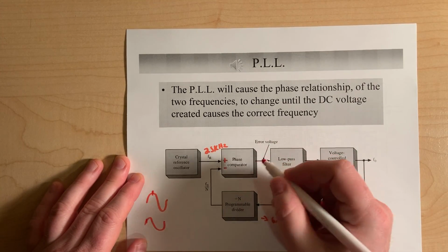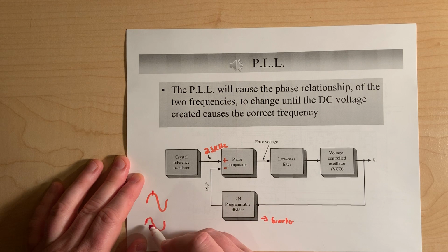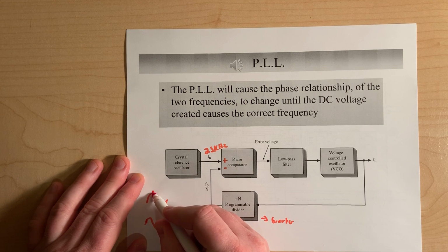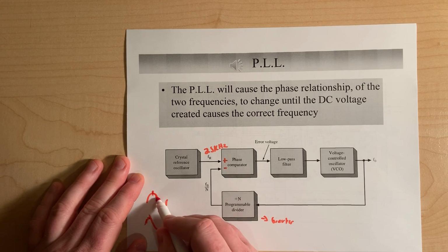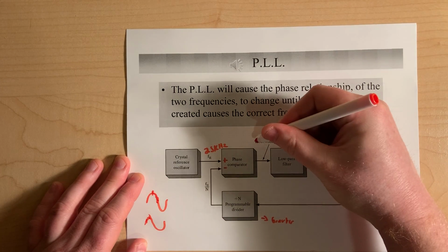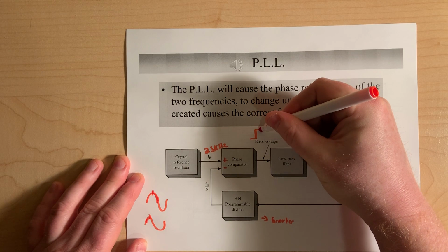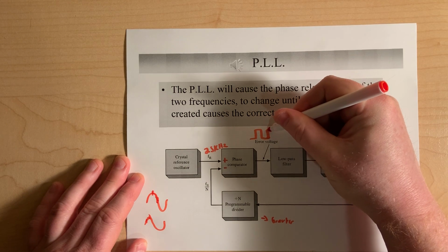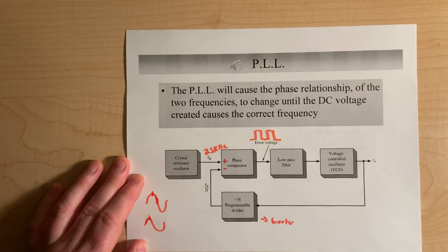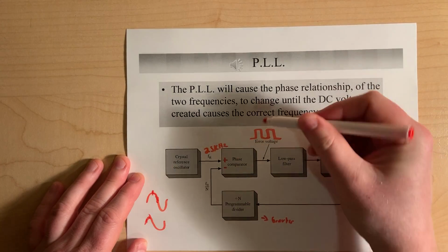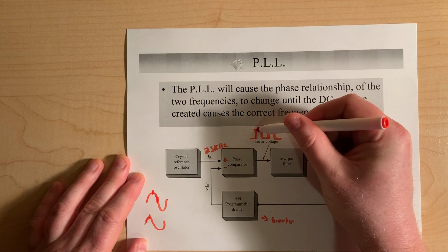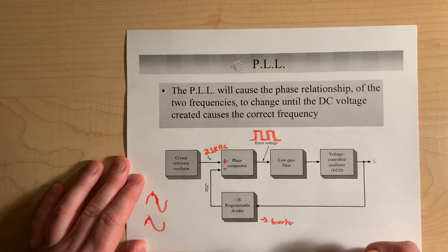And remember what's coming out, and then the same thing's going to happen later on, right? As this guy's phase goes out, this guy comes back, he's at his peak where he's not. So then the output signal is going to look like some sort of repetitive square wave, okay? Depending on how much they're in or out of phase will determine the duty cycle, how much time it spends positive, how much time it spends negative, okay?